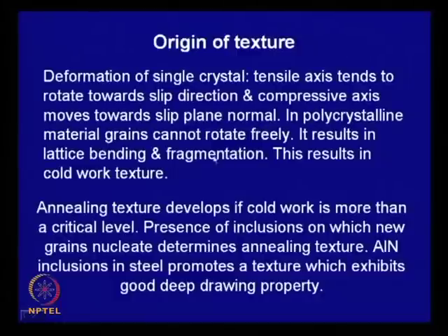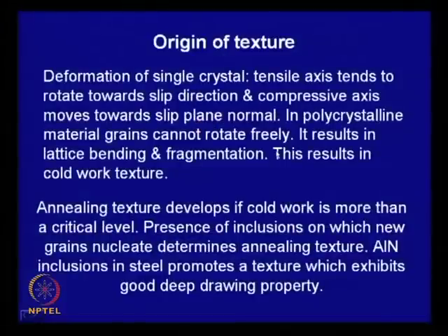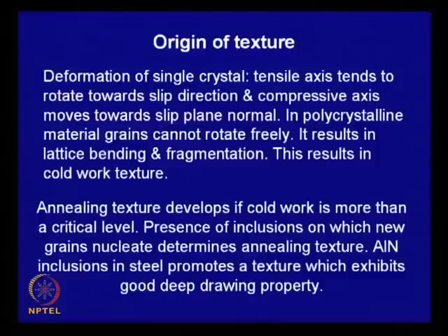In a single crystal this is possible, but in polycrystalline materials there are a lot of restrictions, the grains cannot rotate and move freely, they will get distorted, fragmented, but nevertheless there will be some effect of rotation and you get a texture. This is a cold work texture, so there will be a preferred orientation which is called cold work texture.